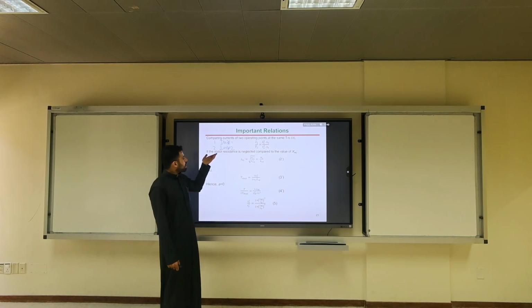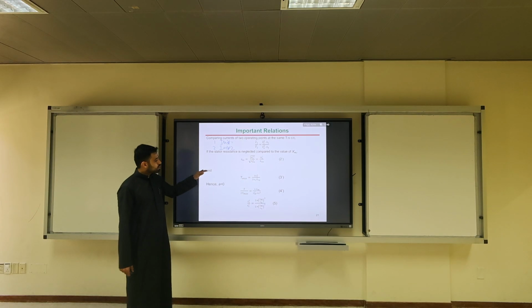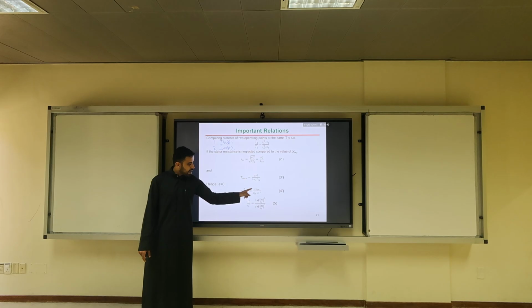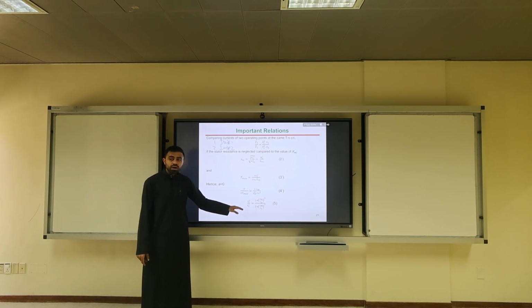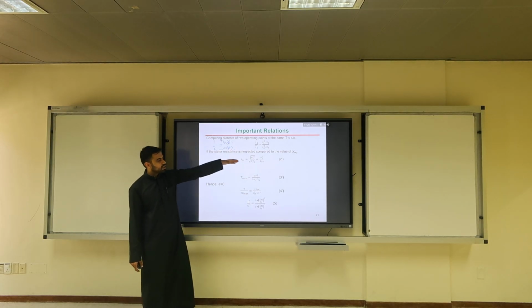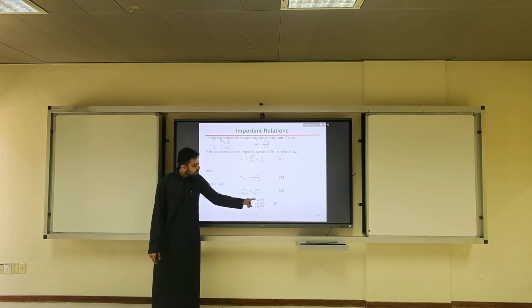This is one ratio. Now let's get rid of R1. If you get rid of R1, you would have maximum slip as R2 prime over X equivalent. Now the torque max becomes a simplified equation. If you repeat T over 2T max, you should get a simpler expression: S times slip max over slip max squared plus slip squared, where S is the slip of the machine operating at slip S. Again, if you compare the two currents, this is slip 1, the slip at a certain speed, and another speed for the same machine, not a different machine. If you add the max, then you reach this equation.